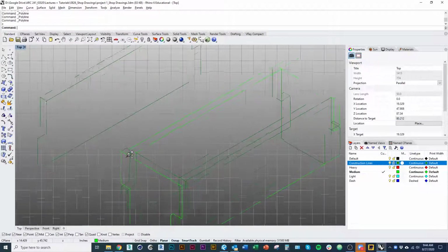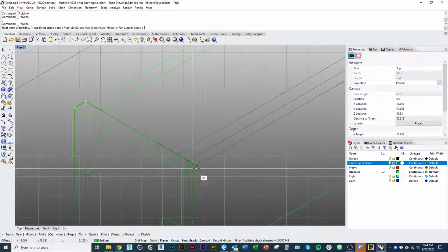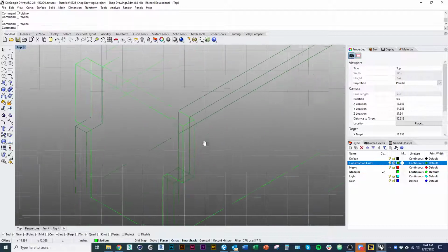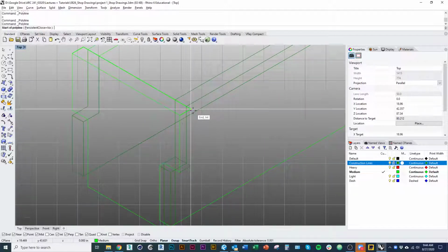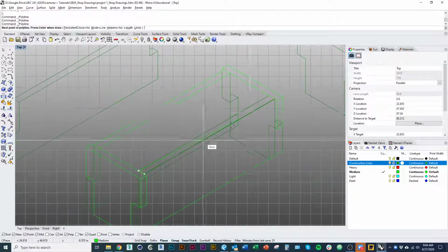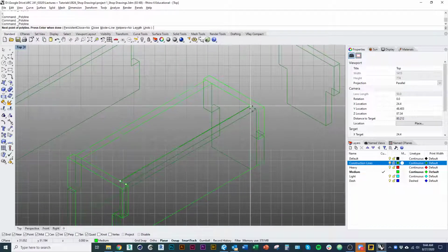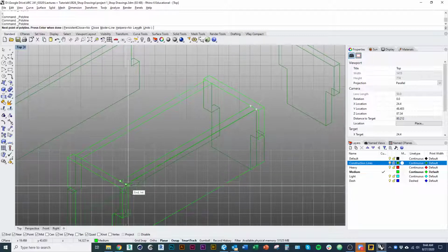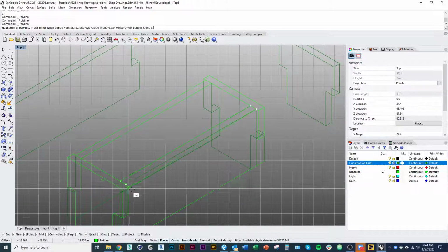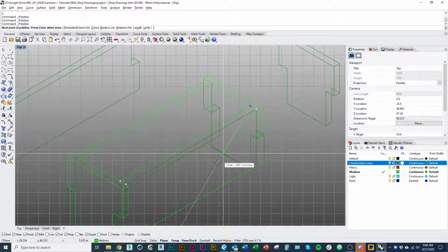And by the way, when you draw with a polyline, one quick trick to use is, if I'm drawing a closed outline, I drew 2 points there, 2 points there. All I'm going to do is click back at the first point of my line to make a closed outline.